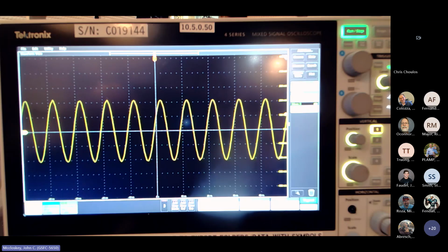But again, temperature effects, any kind of day-to-day variability, you'll have that. I'm not too concerned about half a dB. We're not generally looking for half a dB problems with EMI. So that's the signal generator setting I'm going to use. Okay, so write down 110.5 dB microvolts as the signal generator setting.